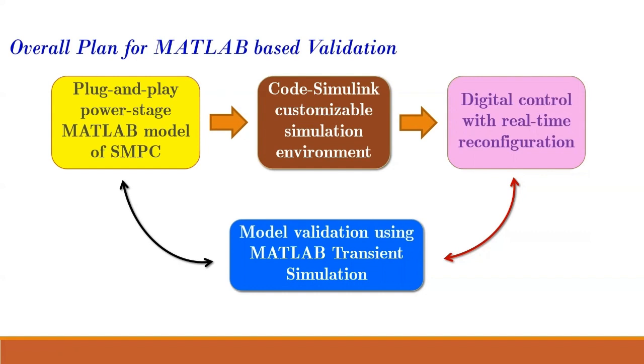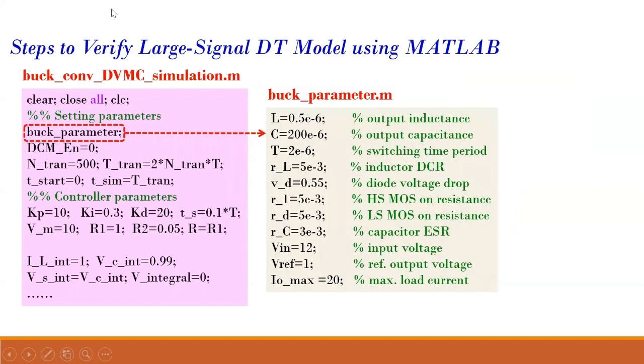It is only in this time we know that it is able to reach the next steady state. Then the closed loop is working. So to verify that the closed loop operation is happening, we perform load transient, input voltage transient, etc. on our model to verify that it is working. So these are the files.